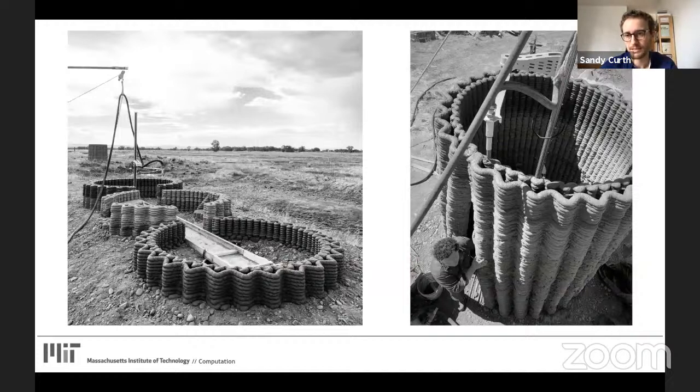And for all of this work, we're using a very simple robotic arm. It's just a 3-axis SCARA type robot. So it works in polar coordinates and is very lightweight. So 2 people can carry it around and position it. To extend our reach, we made a plywood 4th-axis rail for about $60 US, which was maybe my favorite part of this last project. It just had 3 positions and allowed us to work on one structure while the other part of the structure dried in sequence.